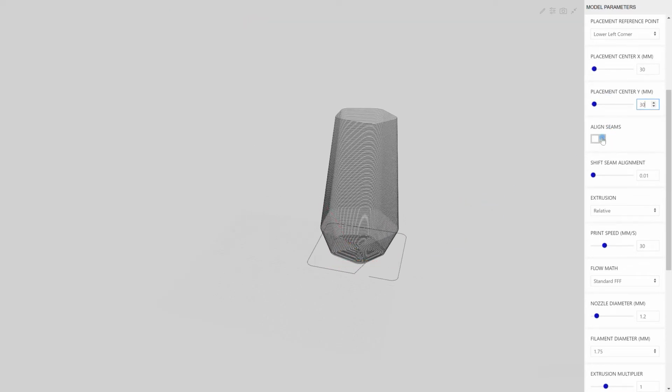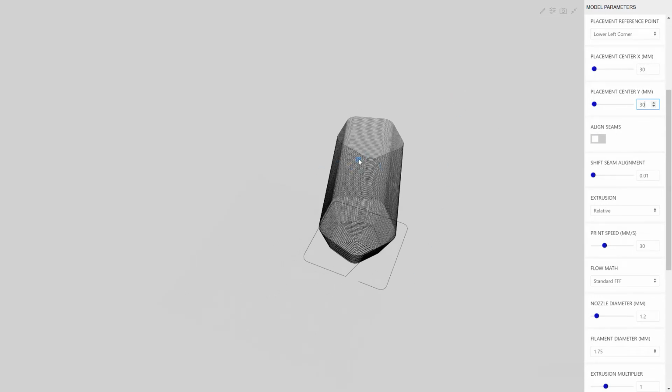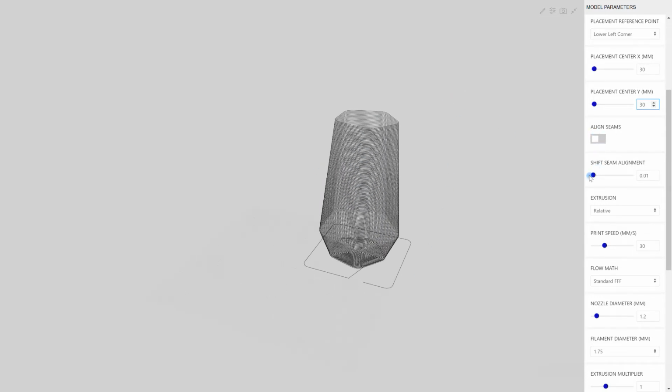The next couple of parameters are used to align the seams prior to the spiralization of the path. They are normally never needed, but in some specific instances where you perform some extreme transformation or use a complex structure or maybe combine different paths together, it happens that the seams are all over the place, and then the spiralization of the path doesn't really work. And you can fix that. You will notice it because you will see something off in the preview, and then you can fix it by aligning and eventually placing the seam where it's best for your spiral.